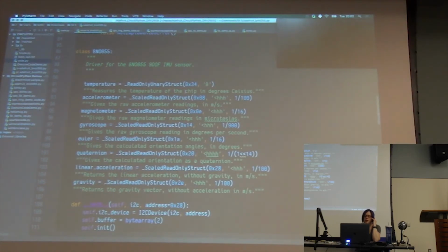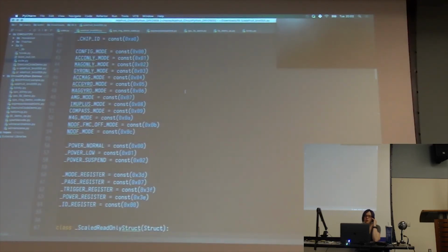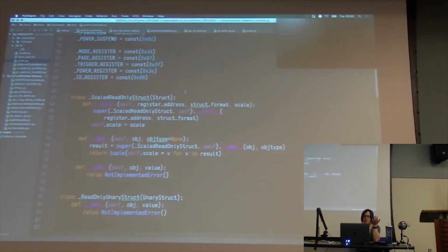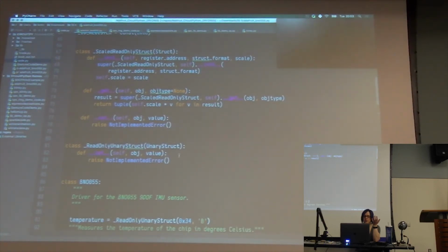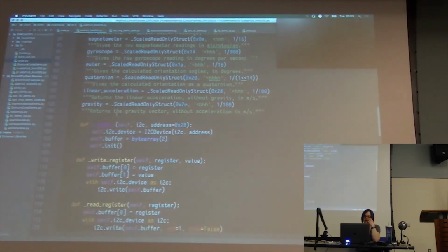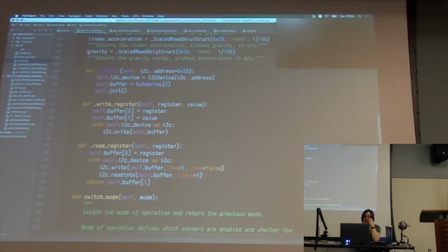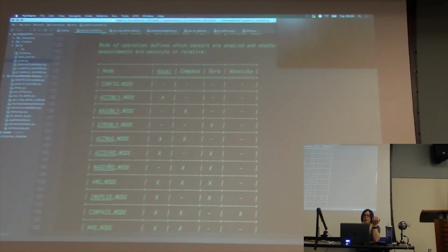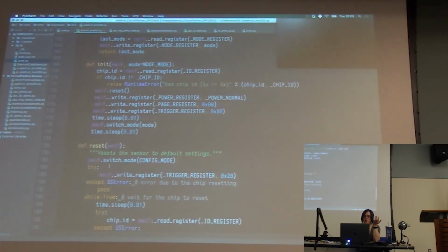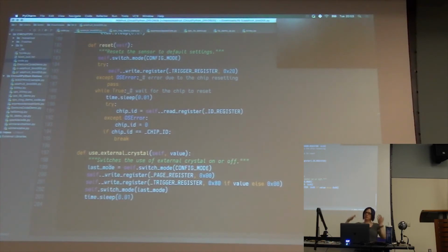So it's reading that data from registers, which are identified in the beginning of the library. And this is what any library looks like typically. You'll have possibly some helper classes here. You'll have the main class, which always has an init. It will have various bits inside of it, depending on what that particular sensor needs. And then sometimes there will be more classes available if, for example, a particular chip used both I2C and SPI. You'd have two different sections in there to initialize those. That's totally separate pins, so it would be wired completely differently, but the driver has everything in it at the same time.